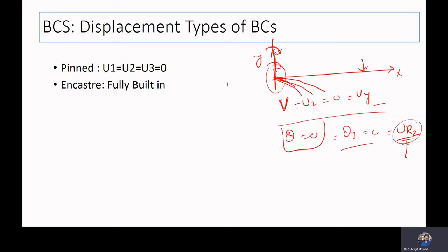Another thing we used to define is your U displacement. Now the thing is, we have a cantilever beam and we are applying a point load which is acting vertically. So there is no load along this direction, so obviously there will be no chance of having displacement along this side. Automatically displacement will be 0, so you can make it 0, or you can leave it.